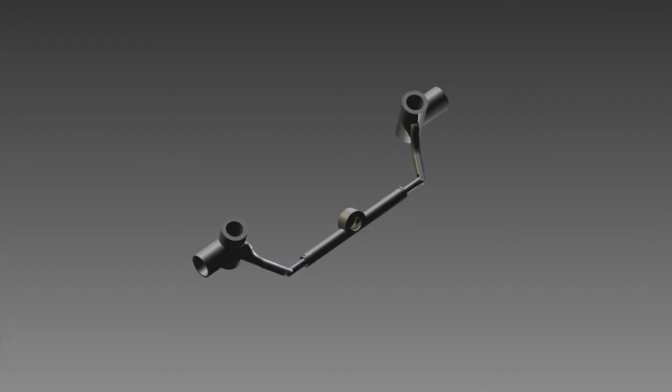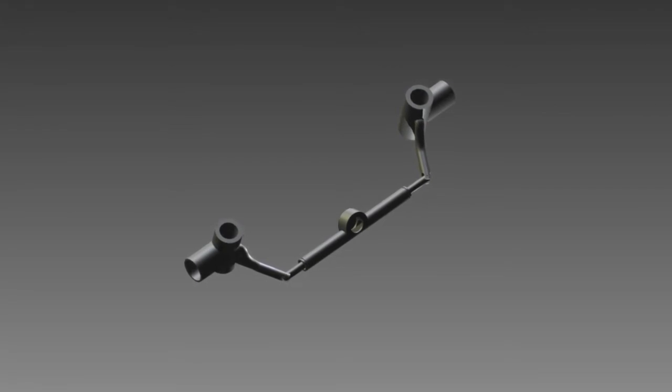I was in charge of the lower steering, which consists of the rod, rack housing, the back housing plate, and the tie rod ends. The lower steering components are also fabricated from aluminum 6061 for, again, its lightweight and durability.